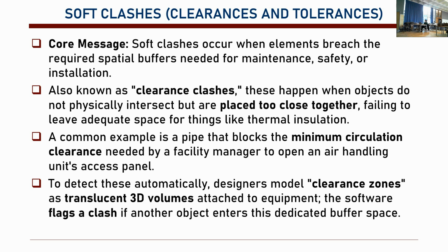And consider that this is a fixed element, and I cannot open this, okay? So the box is there, there is space, but because of that panel, which is, let's say, fixed, I cannot open the box. So this is another clearance. I cannot go in there. I need to be able to squeeze in, and you need a space for a person, and you don't have that, okay? So this is, again, a soft clash, a clearance clash. So we need that, okay?